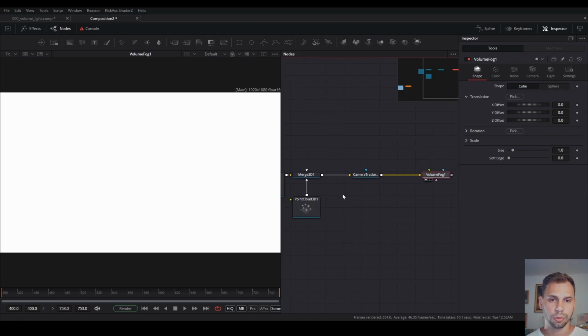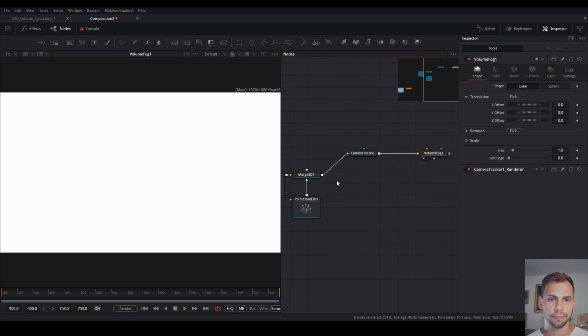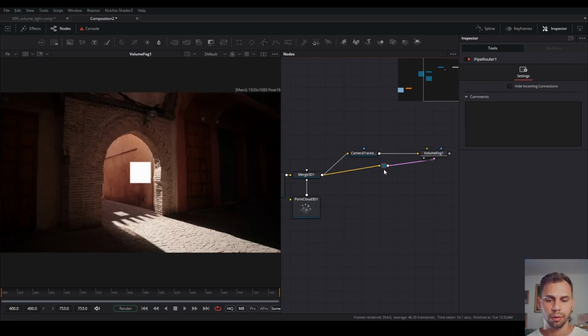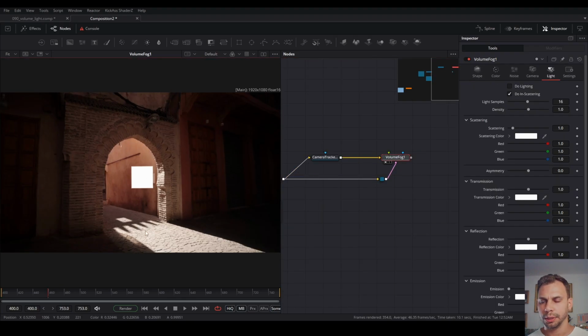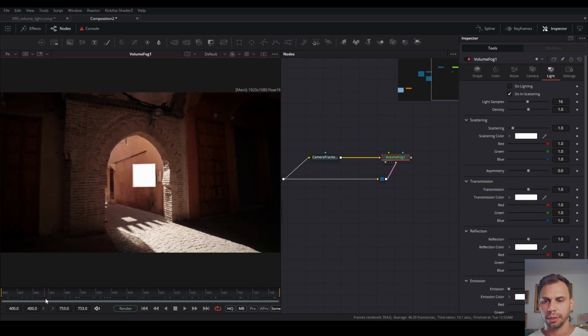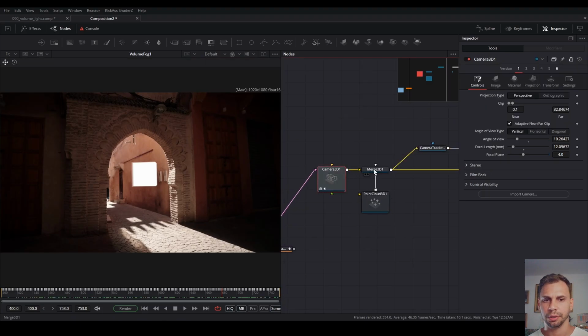And let's also use our 3D scene. So let me move it like this. 3D scene output and plug it into the pink one. By hitting Alt, you can create this node. And so you can see how in the viewport the white box appeared, and this box does not exist in the 3D space here in the merge 3D node.